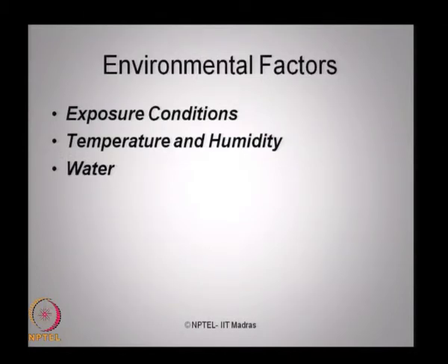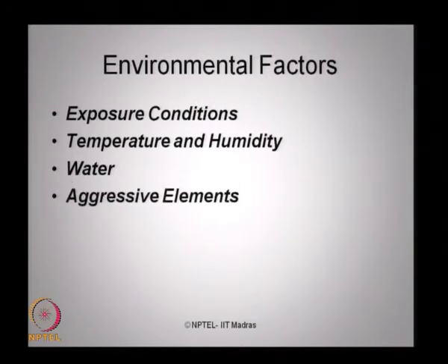Of course, the quality of water, the chemical composition, the biodegradable mass present in water, in sea water in particular, is also responsible for the strength deterioration of concrete. The aggressive elements, which are chemical compounds present in seawater or the chemical compounds which are released during the drilling process etc., can also be equally responsible for strength degradation of concrete when used in marine environment.